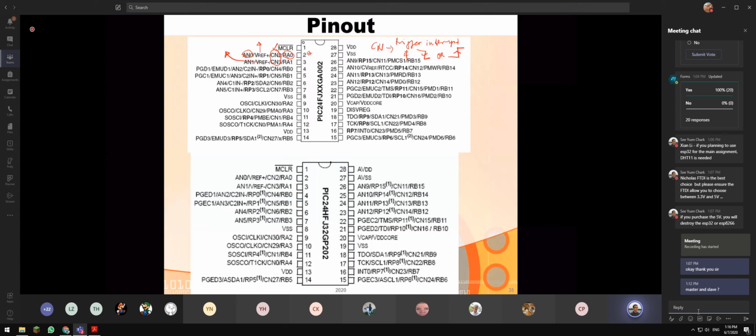So this means that sometimes you're running out of interrupt pins. For example, where's the interrupt pin? The interrupt pin is not in here. So when running out of interrupt pins, that's a reason we can use change notification to replace the interrupt. But remember, change notification has a bit of delay when the interrupt is being triggered. And moreover, both high to low and low to high can trigger the interrupt. So this is one of the major disadvantages.